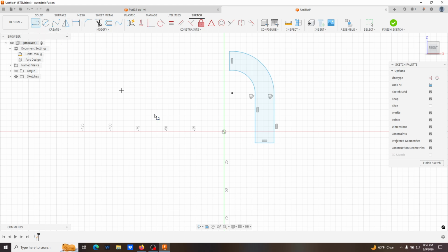Okay. Now, I think I'll use construction lines again just to get it to line up where I want it to. I'm a big fan of construction lines when it comes to modeling things. I'll just model that since I know it's going to work. So I'll go here, I'll press X to make those construction lines, and then I'll make this one horizontal, and then I'll make that one vertical. Oh, it still didn't give me what I wanted. So actually, I want to take another line from here to here, make that a construction line, and then I'll make that one vertical as well.